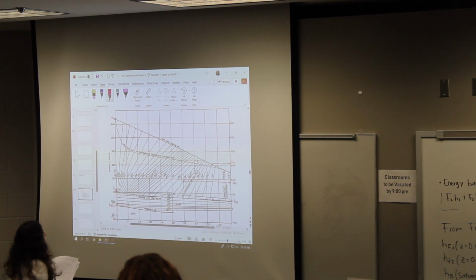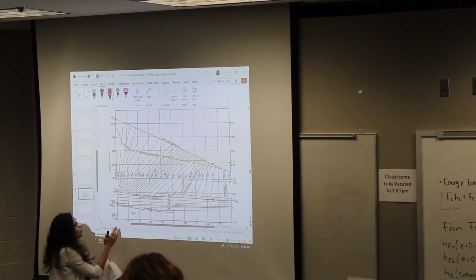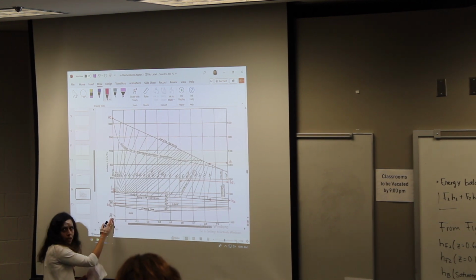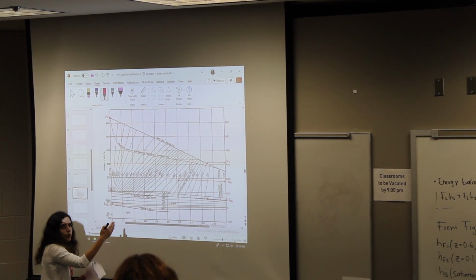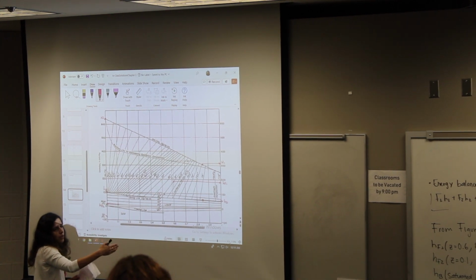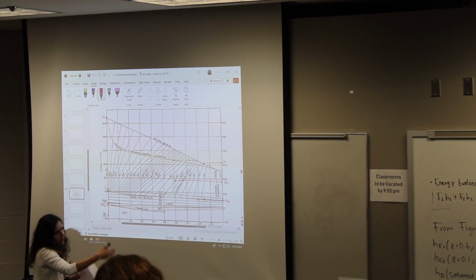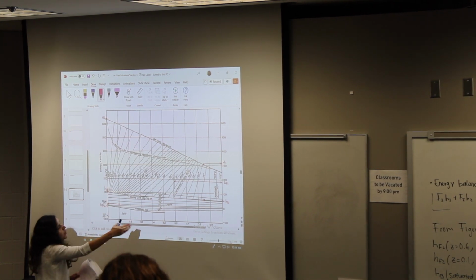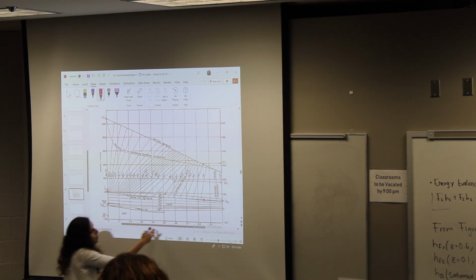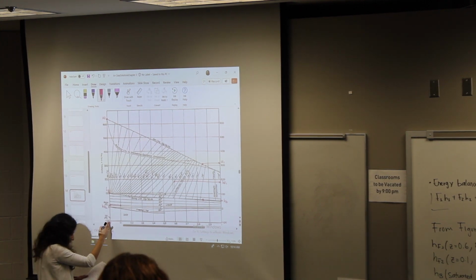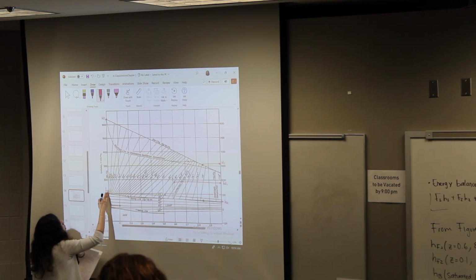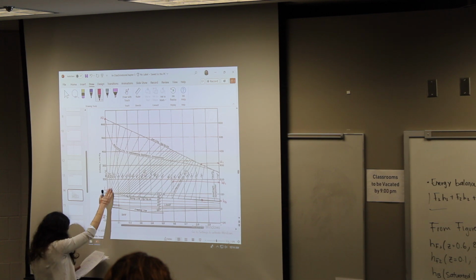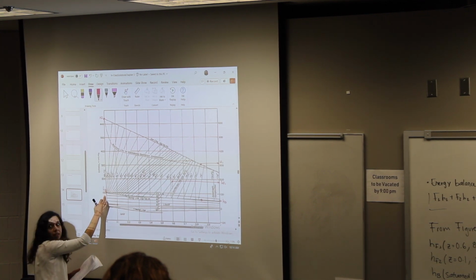Remember Poncho's summary: we will have 100% ethanol here, 0% ethanol here, because it is made in terms of the most volatile component. That's something you need to have in mind in separations. Most of the data is given for the most volatile component. So this summary is built in terms of the ethanol. So 0% ethanol is here, and we have to go to the saturated liquid. So HB is going to be this value of around 100.